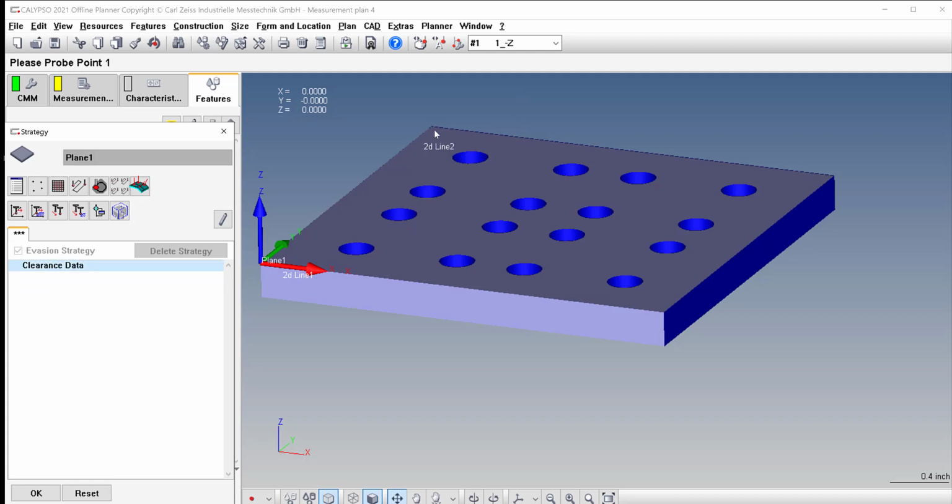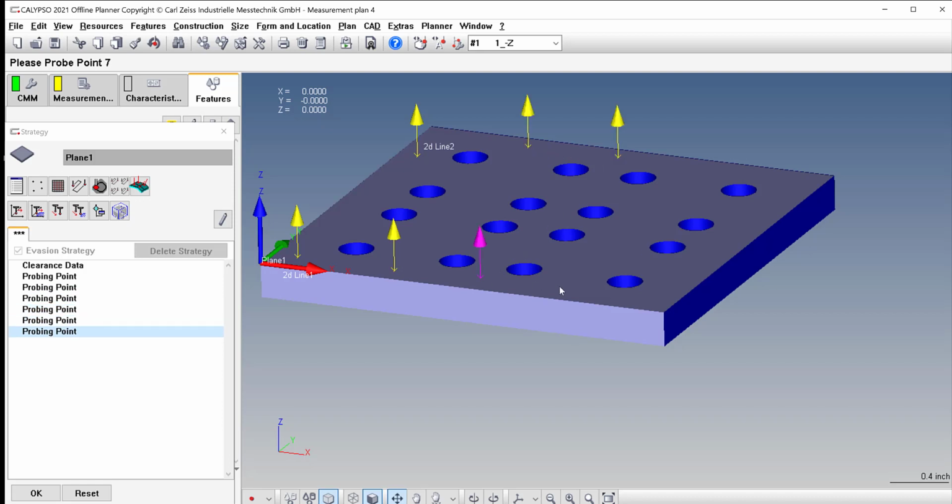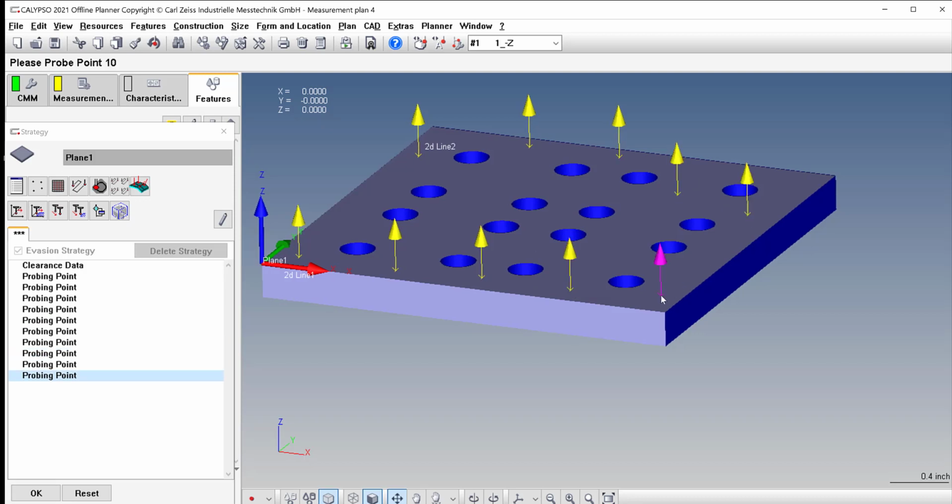Let's say our clamps are here and here, up on the top. So we want to stay away from that area. So we can go here to here, here to let's say here, here to here, then over, then maybe up to here, then over, then here. And that'd be a pretty decent grasp on flatness.